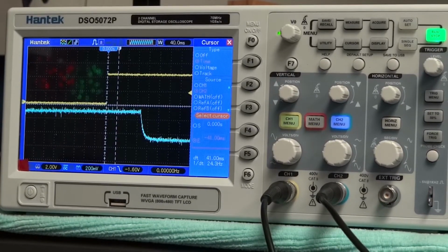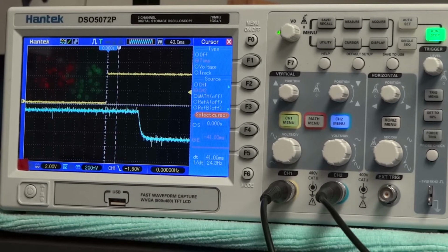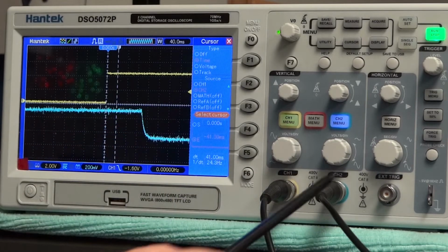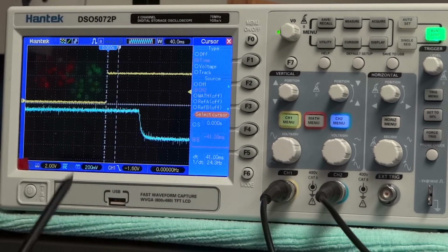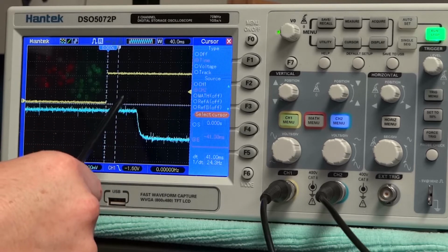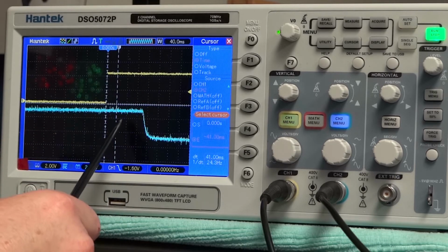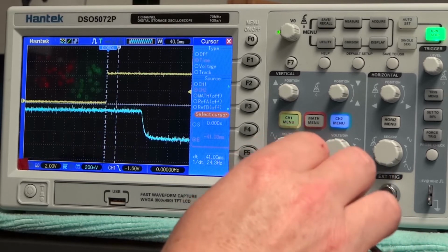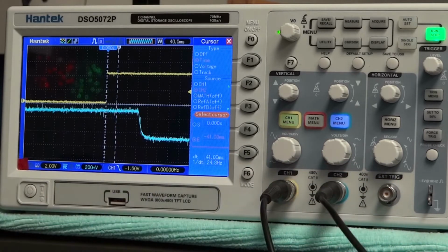Okay, so yeah, indeed, this is looking much worse than the CRT case. Now, since I zoomed out a little bit, the time scale, 1 square is now 40 milliseconds. And you can tell that it's 40, 80, 120 milliseconds or so until you really see a noticeable change in brightness from the photocell. So it looks like ETO was right. Not saying that I doubted him, but better to double check. And the lag introduced by the Scart to HDMI converter is really significant.